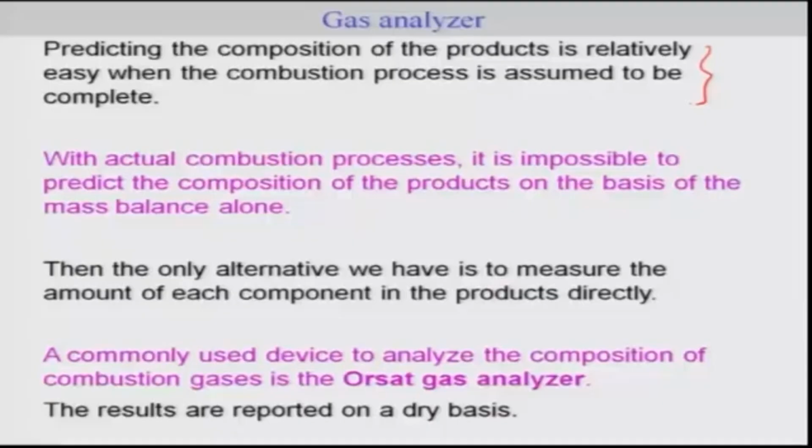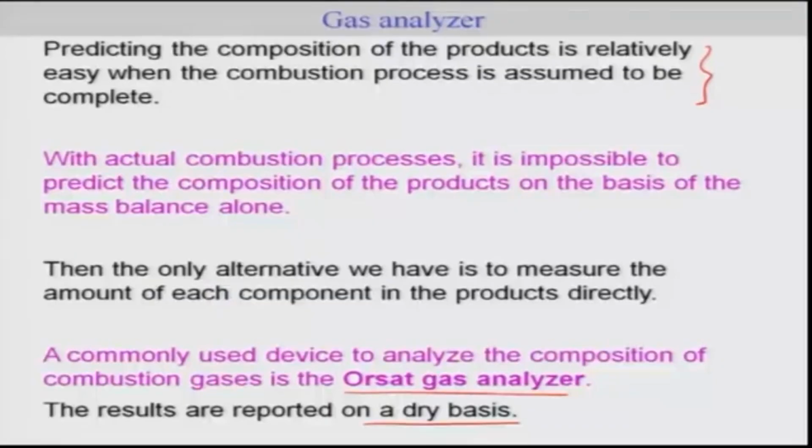This particular analysis is typically done by something called an Orsat gas analyzer, which reports on a dry basis. That means the water is not considered in the analysis. That's the meaning of dry basis. We will be assuming that the composition we have been given is through an Orsat gas analyzer in general. Whether it's a dry basis or wet basis is something which will be provided to us. So this is an example.